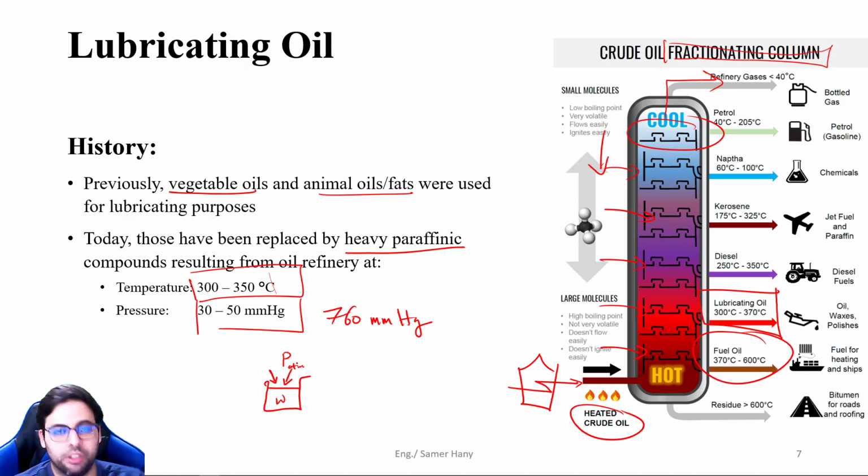So how do we do that? The water needs the energy to overcome the external pressure. So we can either increase the energy of that water by increasing the temperature and hence increasing the kinetic energy and the internal energy of that water, to be able to overcome the external pressure, or help the water out and decrease the external pressure that's pressing on it, or forcing the water to stay in the liquid state.